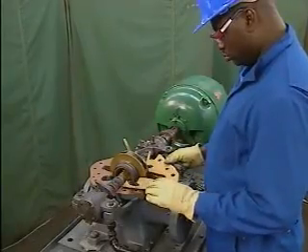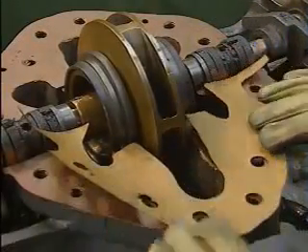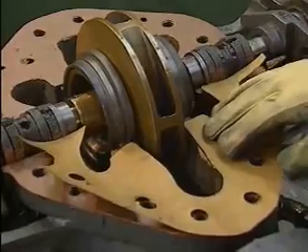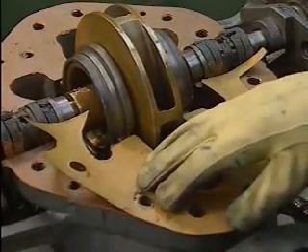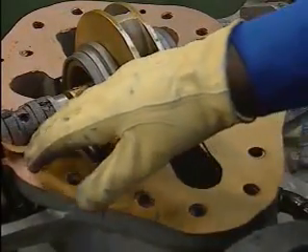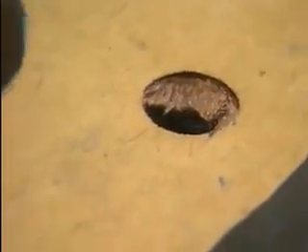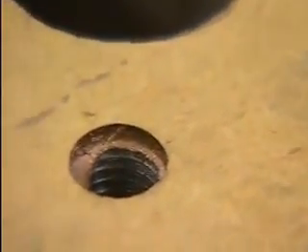The mechanic then places the gasket halves on the sealing surfaces of the lower half of the casing. He carefully lines up the gaskets with the edge of the pump casing and checks to make sure that all the bolt holes in the gaskets are properly aligned with the bolt holes in the casing.